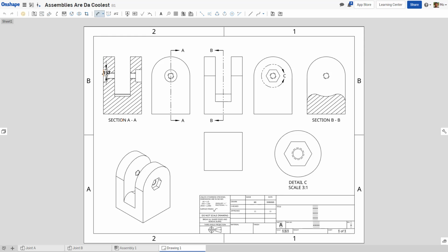I'm going to begin dimensioning now, without much explanation or narrative in between. However, I want to emphasize the importance of maintaining clear and non-crowded drawing labels. Dimensioning balloons should be kept away from other lines and should not duplicate dimensions. Also, consider the person reading this. Don't make the reader do math. The key phrase to remember is be concise and complete.